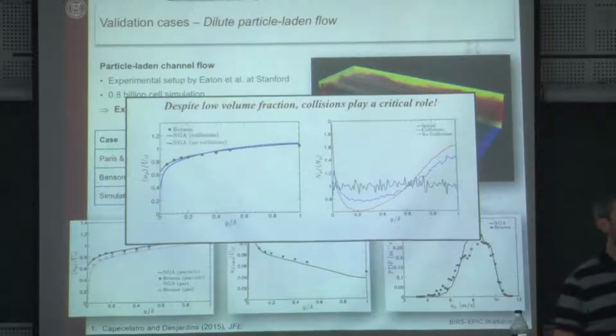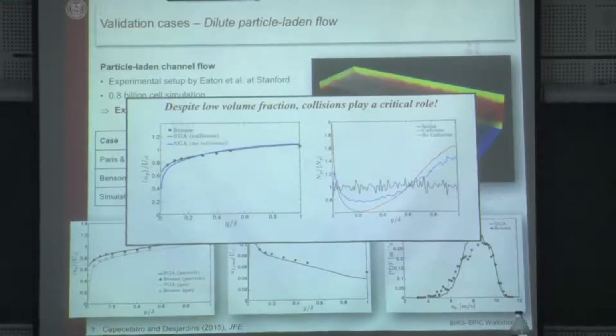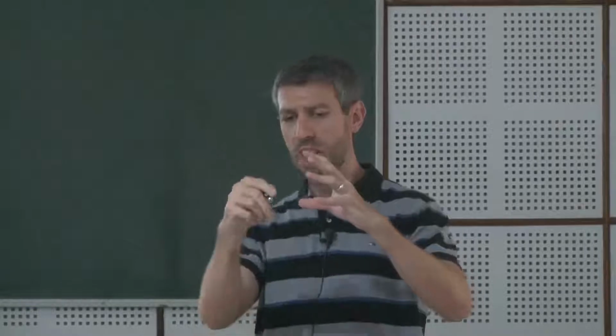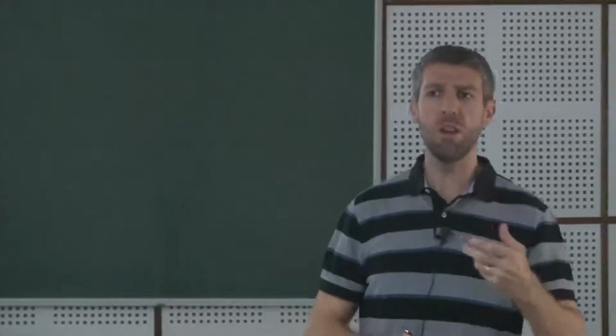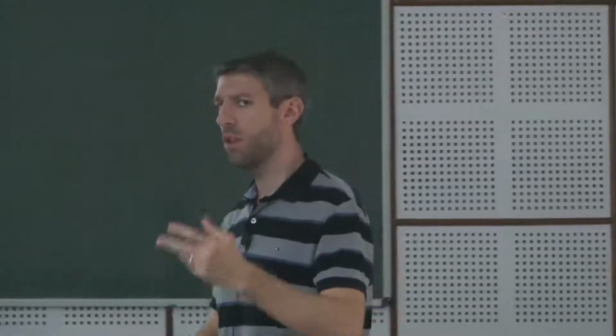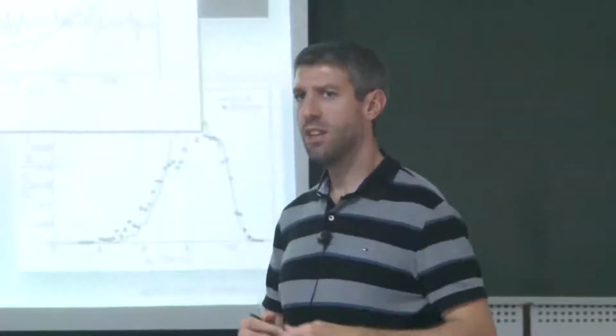And they said, well, the reason for this most likely is the fact that we're not fully capturing the velocity fluctuations at the position of the particle. And that we should really say that there's more fluctuation locally because our averaging process and our resolution is such that we can't. People were doing LES and they were saying we don't have the full fluctuations. When I interpolate my fluid velocity to the particle location, I'm underestimating the amount of fluctuation that the fluid imparts to the particle. This was their argument.